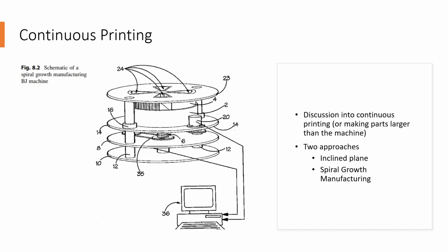The second approach utilizes a circular powder bed with constant rotation and continuous binder printing and recoating. While in motion, the powder moves down the spiral continuously to make room for the next layer. Moreover, the top layer creates a spiral in the powder bed. There are also several build stations that each contain a print head with multiple nozzles. A side effect of this design, however, is that the images printed must be pre-skewed to compensate for the differences in speeds of the powder bed.